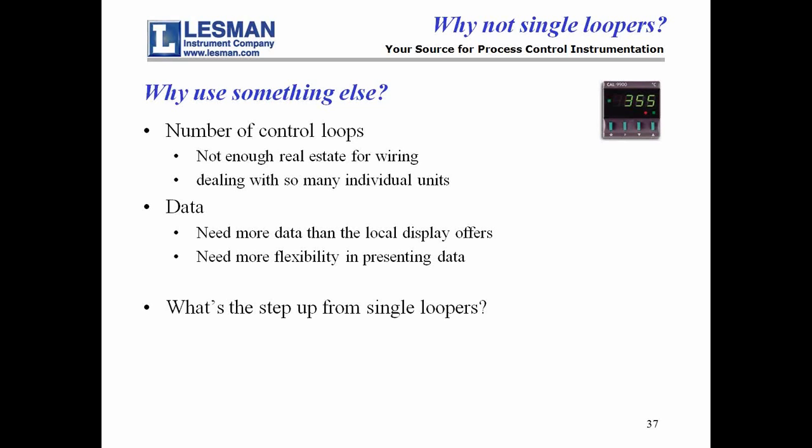It's done on a rack with modular control. It's in the panel and it's blind. So because it's blind, we got to put something on there to be able to see what's happening. That's the operator interface, the HMI. That's classically either a panel HMI with graphics or it's a PC monitor that talks to the control system, which is running through a PC somewhere.